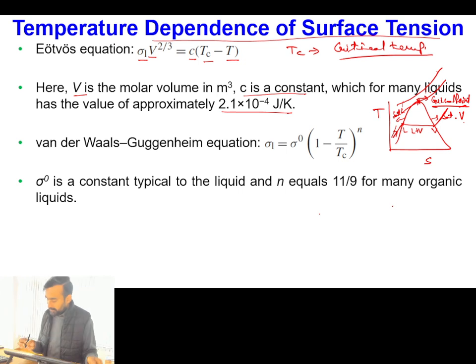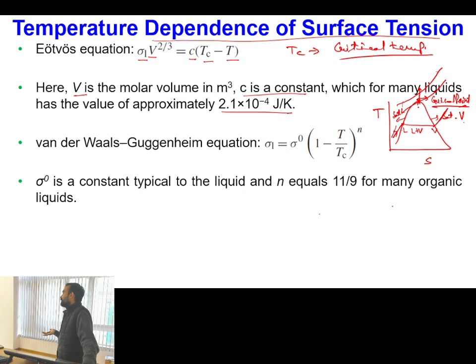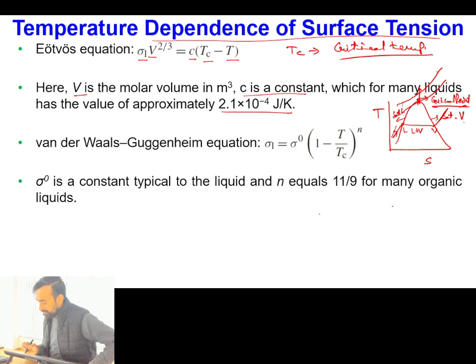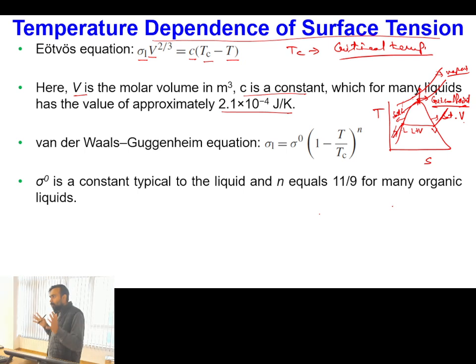Typically above the critical point, the state of the substance becomes such that we cannot make a clear distinction between the liquid and the vapor unless we are physically verifying it. In other words, the molecules in the vapor state also become so close to each other that their intermolecular spacing becomes identical to that between the liquid molecules.